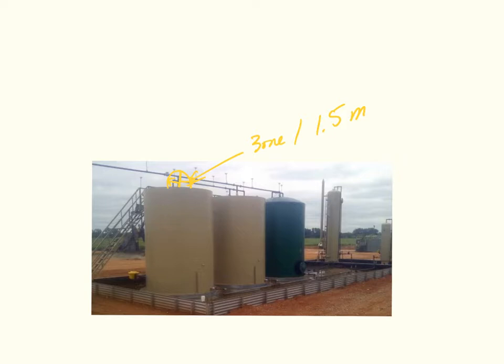So 1.5 meters in radius out from that is that Zone 1 location. Now from there we go into, of course, a Zone 2 location, and that Zone 2 location goes like this. And it actually extends all the way down and over to the dike wall. It's important to note that inside that dike is also considered a Zone 2 location. And that Zone 2 location, I might add, is at 3 meters.